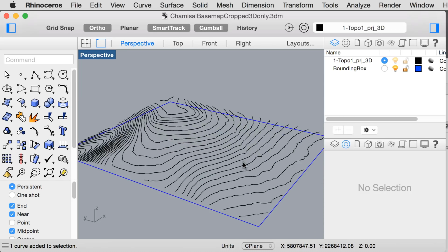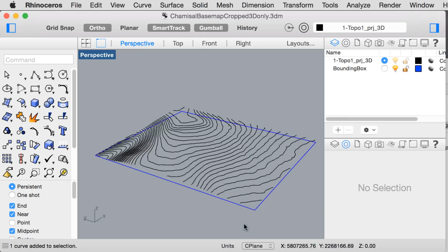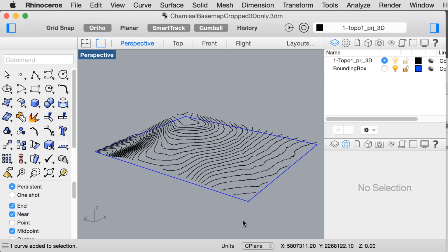In order to make the pancake model work well, it's best if you have a boundary around your contours. So instead of having miles and miles of unbounded topography, which you may get, for example, if you bring the contour lines in from a GIS program, I would like you to put a rectangle around a particular area so that maybe you have something like 1,000 feet as opposed to many miles, and then trim off any excess contour lines beyond that box.